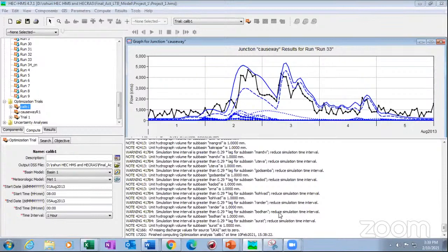Sometimes such a huge model is not required for simple simulations. In that case, if you develop certain simple models, like empirical models, you can compare them with the existing empirical models in HEC-HMS, and you can prove your theory, how well it suits a certain area, right? Many SCS CN methods were developed maybe for foreign countries. For your country, or particularly your area, you may want to optimize or develop a new technique for the computation of the unit hydrograph, or the runoff modeling technique. So you can develop your own model for computation of runoff, and then compare here also. That way you can do it.